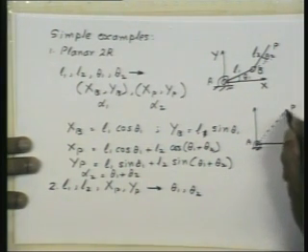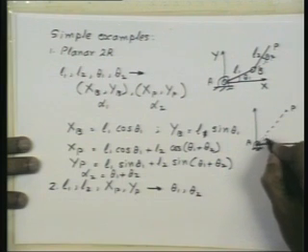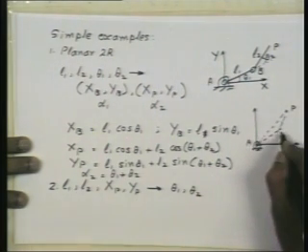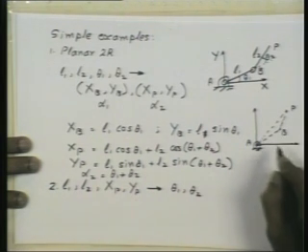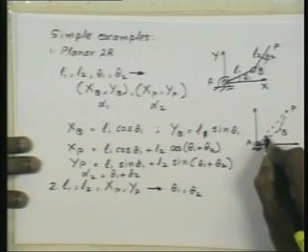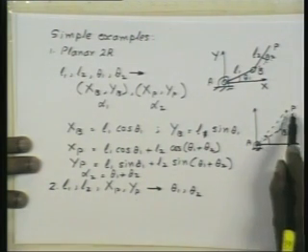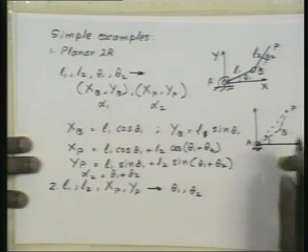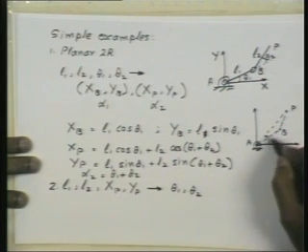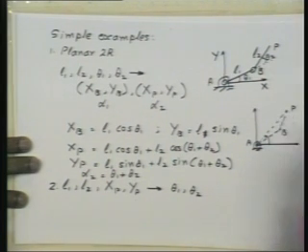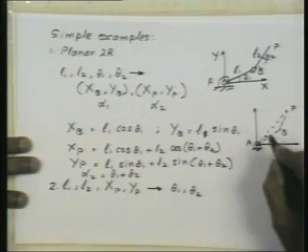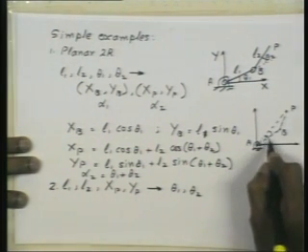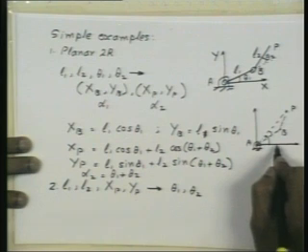If you draw the mechanism in some position and also connect P to A, this is B, right? This angle can be easily calculated because we know the position of P, correct? And now look at this triangle ABP. All sides are known. So this angle also can be calculated, right? So this angle minus this angle will give me theta 1.